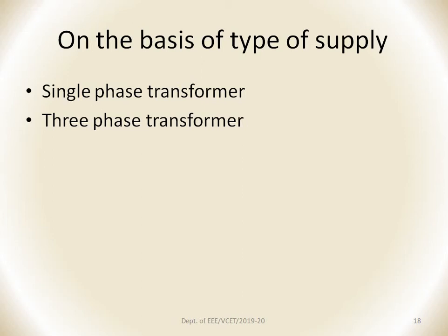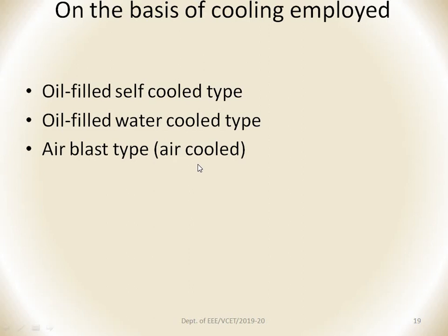And on the basis of the supply, it can be classified as a single-phase transformer or a 3-phase transformer. And based on the cooling arrangement used, transformers can be classified into oil-filled self-cooled type, oil-filled water-cooled type, or air blast type, which is otherwise called air-cooled.